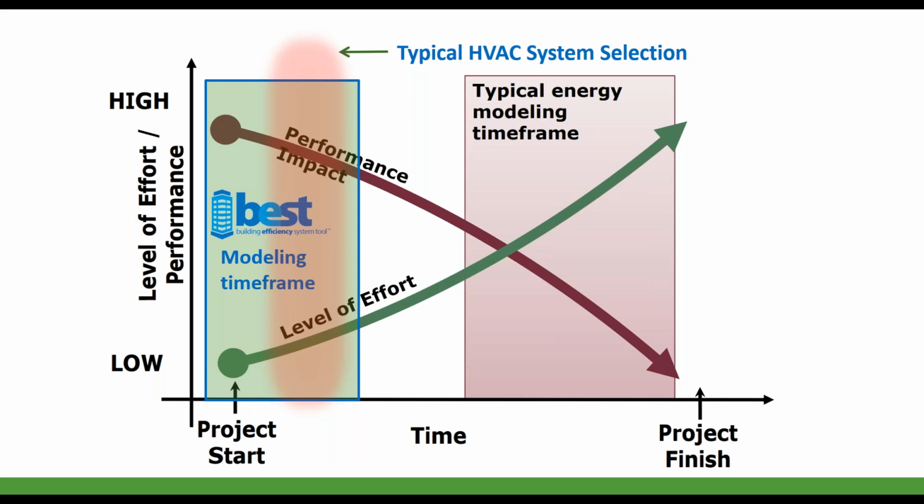Now, let me be very clear. BEST is not a replacement for the EnergyPlus and the TRACE and the other full-blown energy modeling frameworks. What we're really trying to do is look at HVAC systems, look at budgeting, some costs, some life cycle costs, and just provide a comparison at a very early design stage for that design team to at least have a conversation about, hey, what type of system should we put in here? What should we take a look at? If we're going to take a look at 2 or 3 different systems, how do they compare to each other?